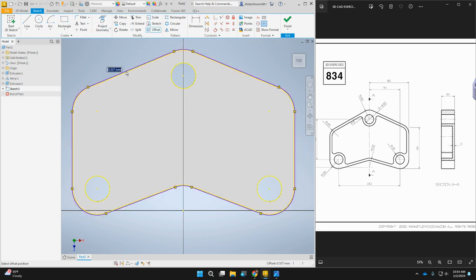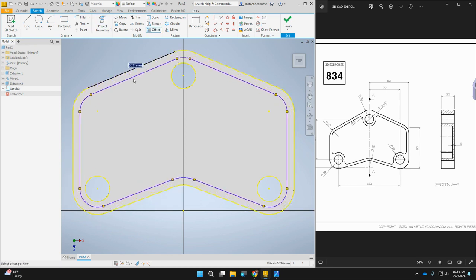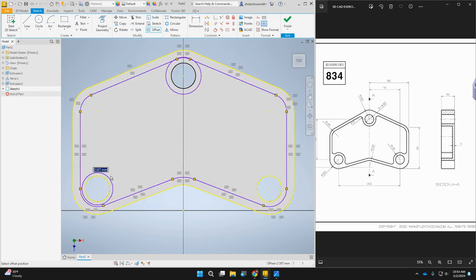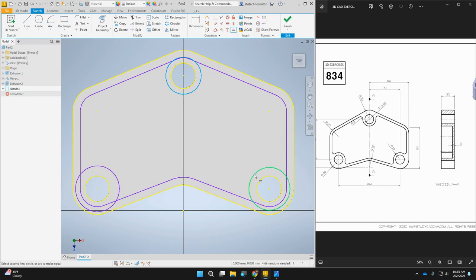So when I click on offset in there, I can bring this in, and then I'm going to offset each circle. I could just draw circles off that center point, but this is easy because I'm already in the command. We'll make those all equal to each other, and we need an offset distance. They don't really give us one. Normally there should be a measurement on the thickness of this wall somewhere.